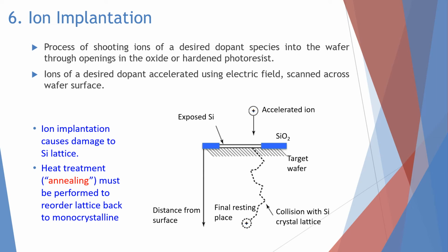As we already have the N-type Si wafer, now we want to create the P part. For this, we have to perform ion implantation. Ion implantation is a process where we shoot ions, which are accelerated, at the Si wafer. They enter through the opening, the part without the oxidation layer, and go into the Si wafer. Then they are placed where they are supposed to be.